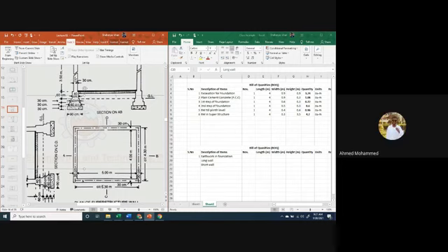Okay, sure, sir. 5.2. But we are working at this level. So 4.3 plus half width, which width is 90 centimeter now, 0.9. Yes, sir. So the length will be 5.2. 4.3 plus 0.9 is 5.2. Now, what is the length of short wall?